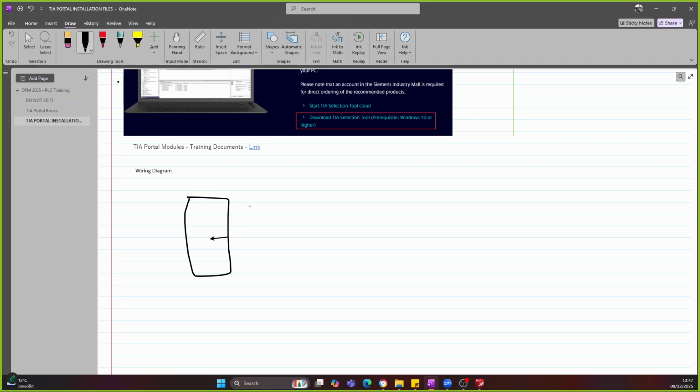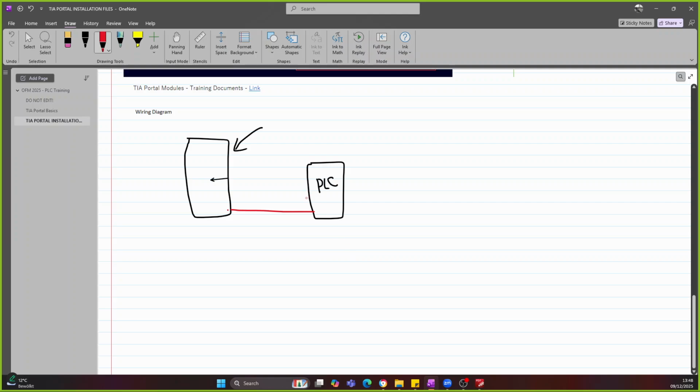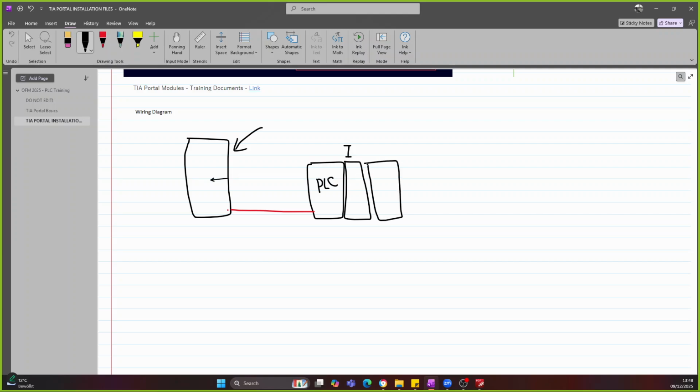And then you say, when you come into the house, when you open the door, you want your PLC, this is the PLC, you want your PLC to start, to switch on the bulb, basically. So it means there should be a connection between your door and the PLC, right? And on your PLC, that connection should actually go to your input card. You know, we talked about I/O. So this is an input card. Let's say this is an output card.